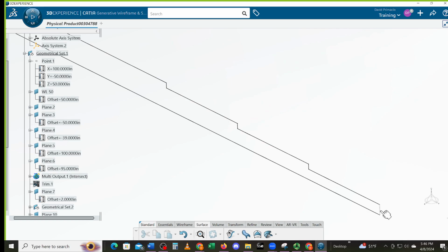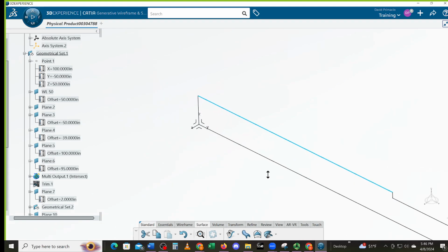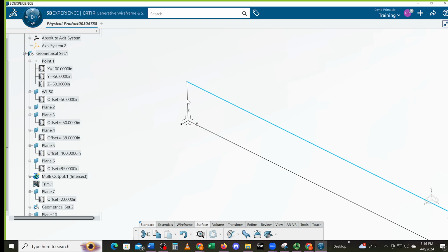Because when you try to delete that line, you click delete once, and then the second time, you should have deleted the line that you created from. So the first time, you're deleting the trim, and the second one should have deleted the line. So you have a double line on that.